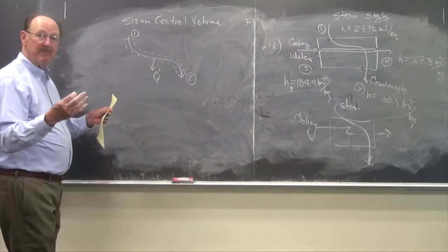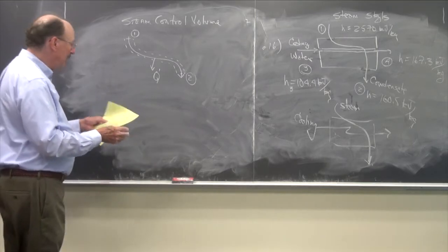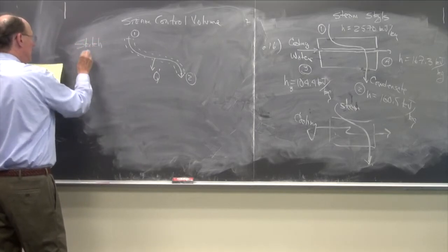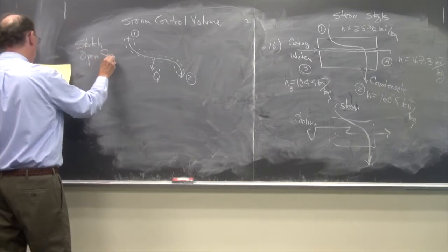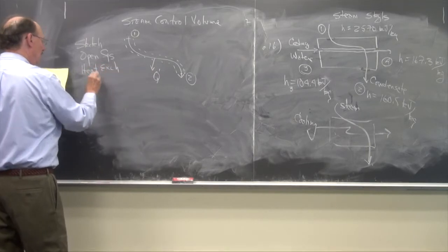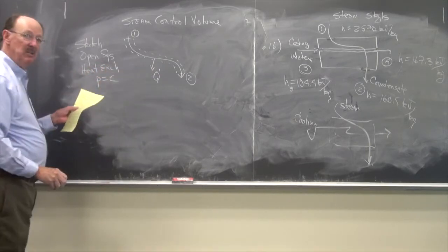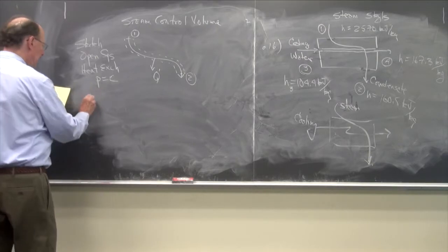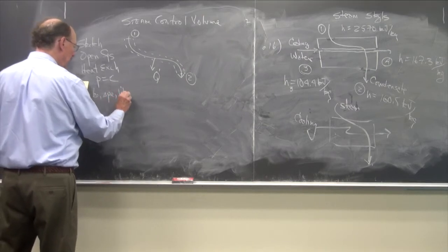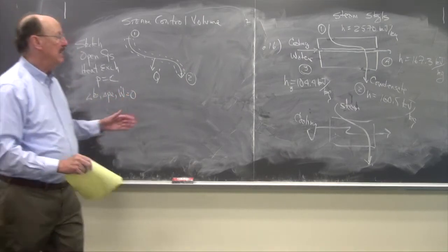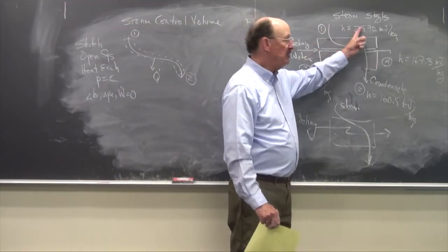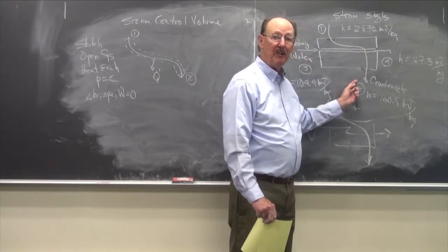So I can apply a first law to this. Now I drew a sketch. We have an open system for heat exchangers. Pressure is constant ideally, and delta KE, delta PE, and W dot are equal to 0. We aren't given information about velocity, nothing's moving up and down, and there's no paddle going in or out of the system. You have to think about that.